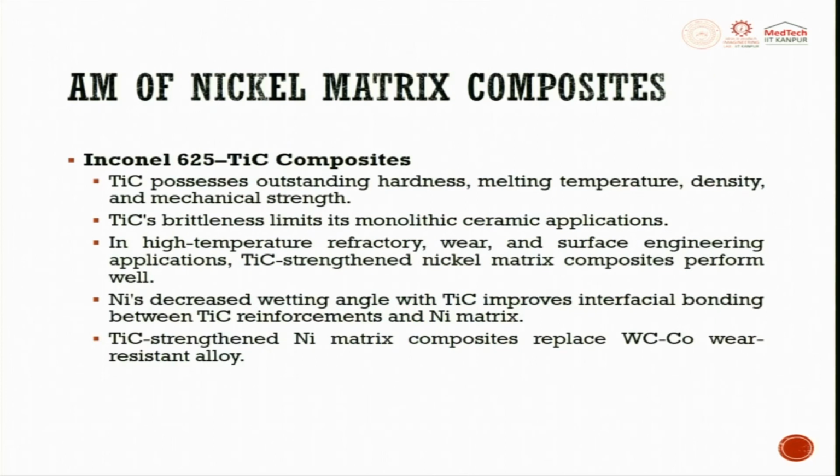Nickel based alloys include Inconel 625 reinforced with TiC. TiC possesses outstanding hardness, melting temperature, density and mechanical strength. TiC's brittleness limits its monolithic ceramic application. In high temperature refractory, wear and surface engineering applications, TiC strengthened nickel matrix composites perform very well.